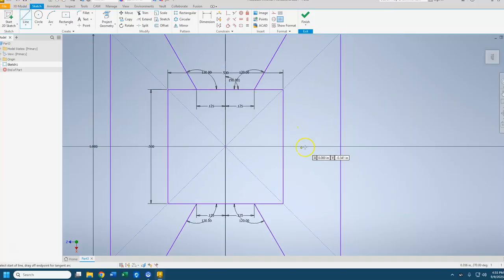So I'm going to grab my line tool, and I'm going to come up 1/8, and then I'm going to close my tool. Because right now, it was making it so that way that angle was pulling, this was either 90 or 180. So right now, this counts as 0. So now I only need it to be that 60 degrees. So you need to be looking at where it's considering to be 0. And that's what's going to help you about your math.